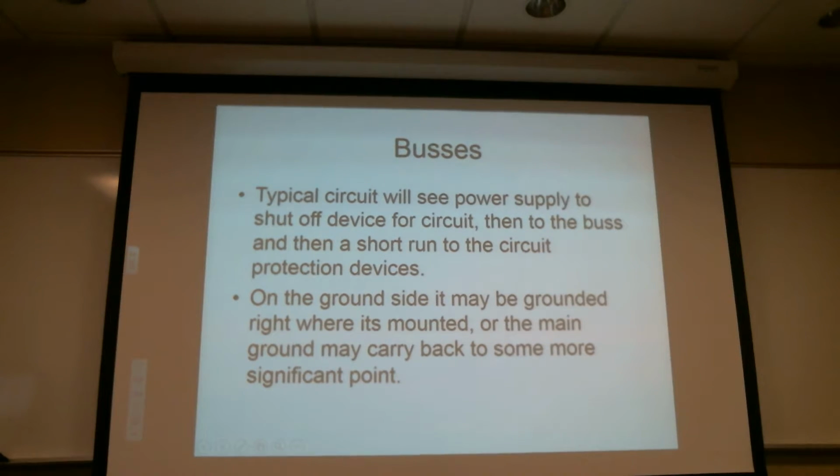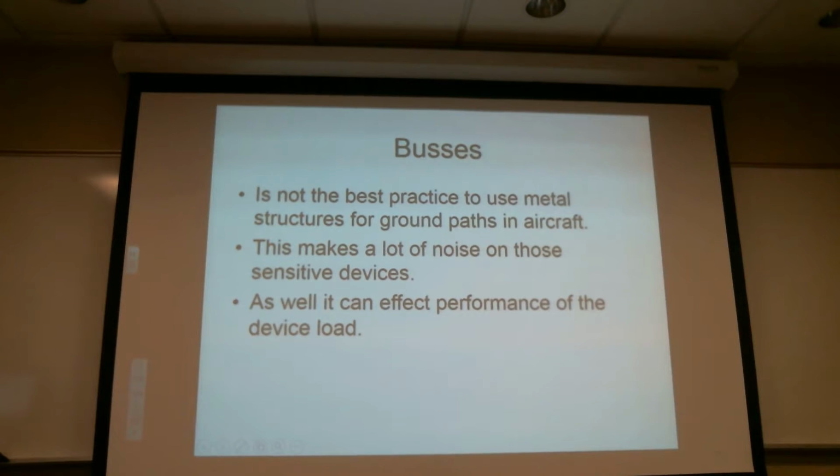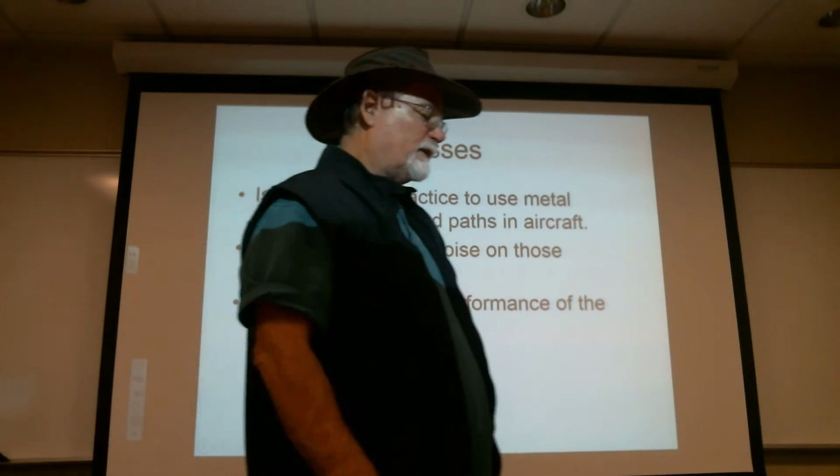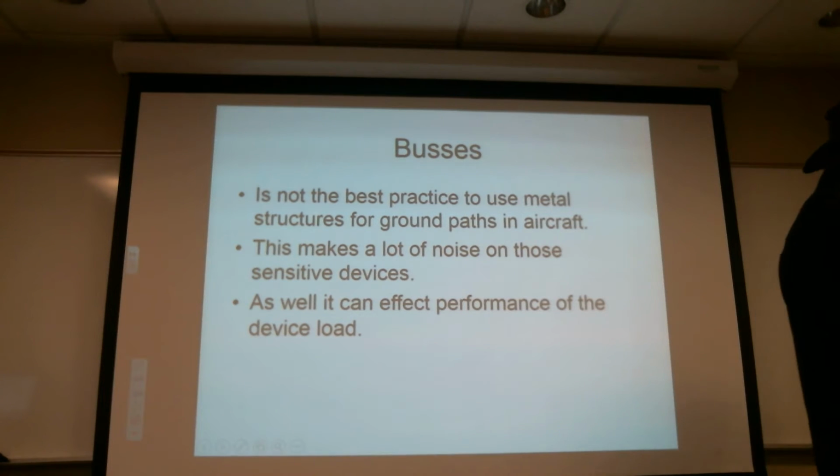So yeah, it's fairly typical, if the battery's in the back, to ground it to the airframe. Oh well, that's what they do. I don't recommend bringing the ground back through the chassis of the airplane. It's a viable thing to do where RF isn't an issue.